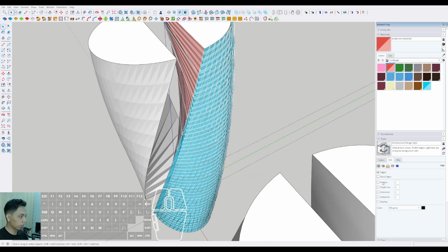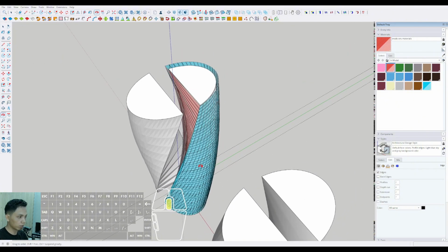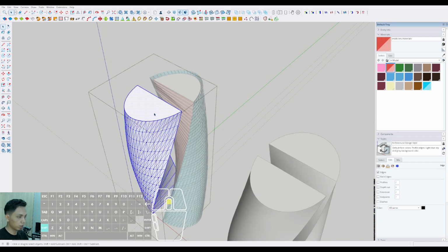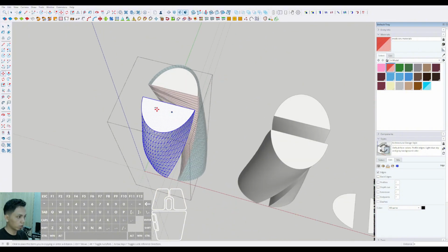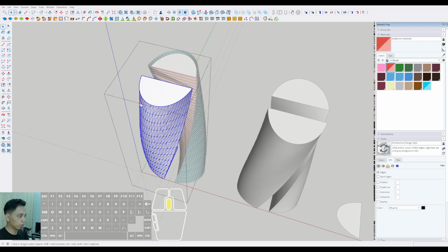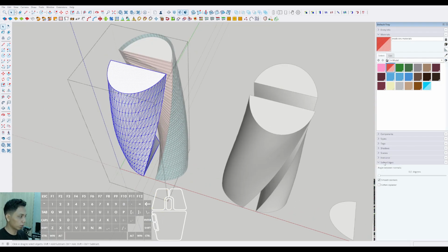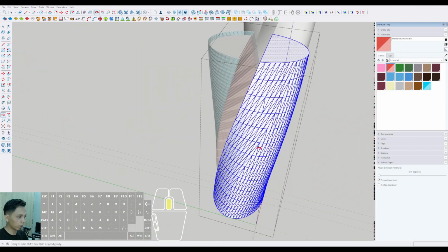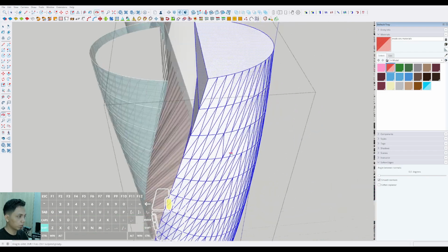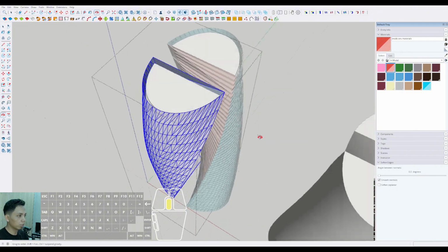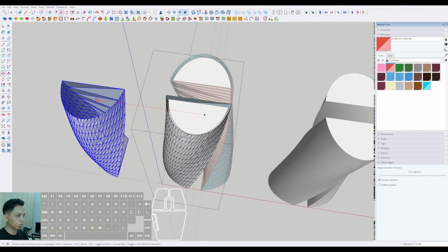I just uncheck the profiles, because if the profile is checked, it would make my hardware too heavy. Okay, now we can select this envelope and select duplicate, select move, press Ctrl until this position around 200 meter. Enter. I'm sorry, I have to make the soften edge first. You can click this soften edge on the right side toolbar. You can drag to the left side until the frame with lines appears right there, and delete the top surface.